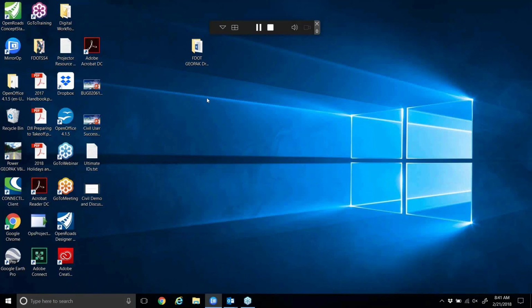And then as we go over to the top of 1-3, you've got your geometry database. That's typically in your roadway folder. So we will have a roadway project, and it's going to point out there to the GPK file. That's going to contain all of our roadway geometry, and the main thing we're usually looking for is our alignments. So that GPK file is going to contain our alignments. And then the last section here, really in this class, since this is not doing the plans preparation portion, it's not really using many of these criteria files, if any.